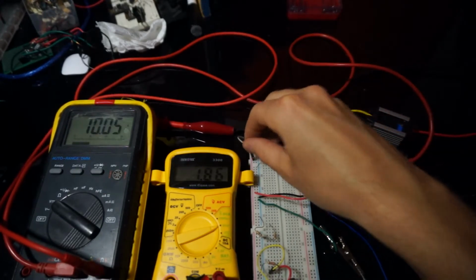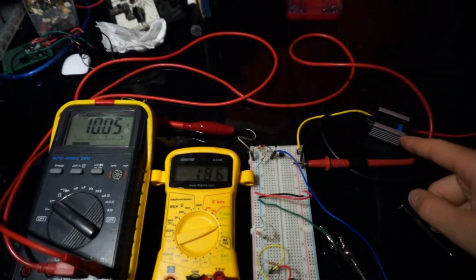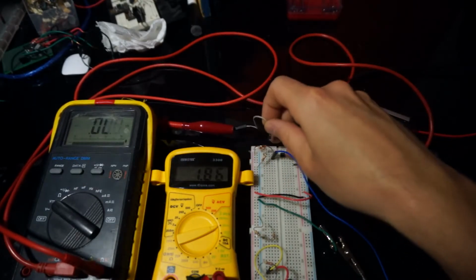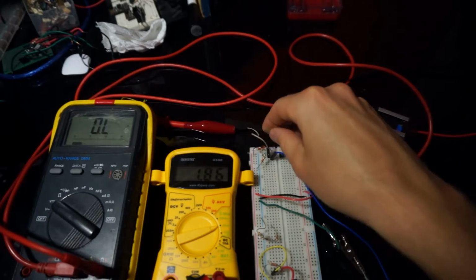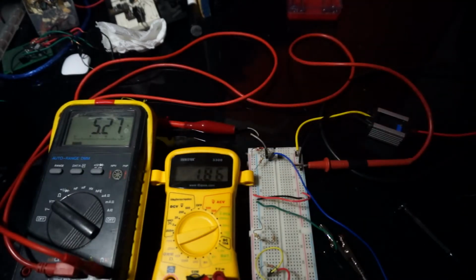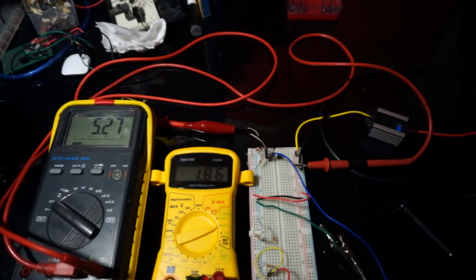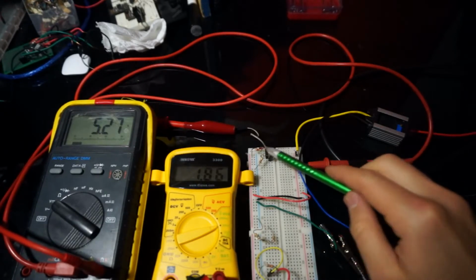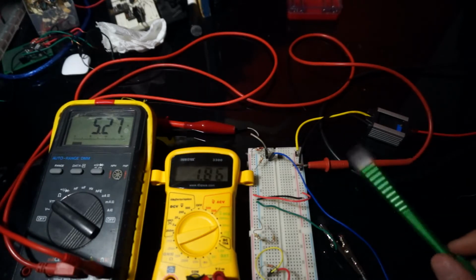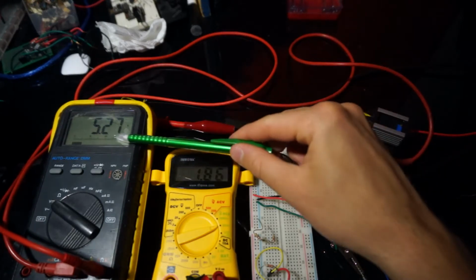Right now I have a 10 volt supply from my little handy buck converter, and I'm just going to first probe the diode. I guess this is the base voltage here, is 5.3. And I just looked back at the schematics, and I lied to you at first. The 1N4733 diode, which is what this guy is here, has a 5.1 nominal Zener voltage, which is why I'm a little bit puzzled.